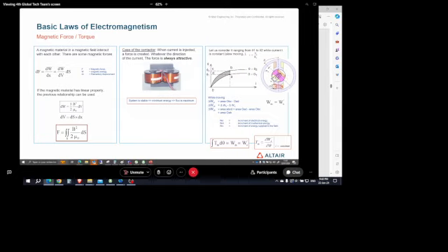So then, when the rotor pole is aligned on the stator tooth, this is where I have the maximum flux, and this is where I have zero torque actually, right?